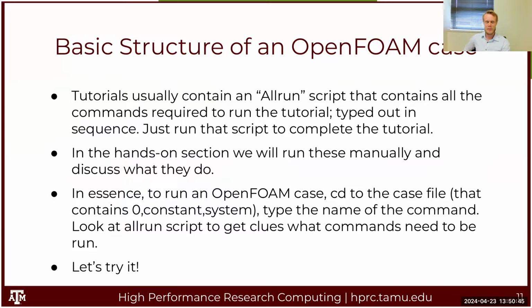Okay, as I said before, when you download OpenFOAM or when you load OpenFOAM on the cluster, it contains a lot of tutorials. Each tutorial comes with a script called allrun that contains all the commands you require to run that tutorial in sequence. So you basically just have to run it, and the tutorial runs, and then you're finished. But that's a little bit cheating, and it's not very educational. So for today, we're going to do a tutorial, but we're not going to use the allrun script. We're going to manually run all the commands and discuss what they do.